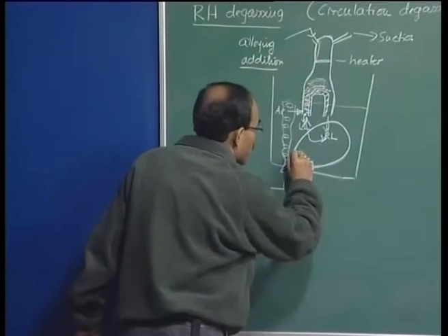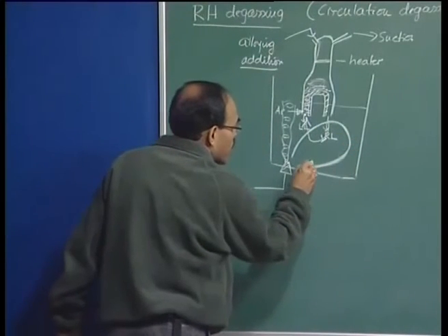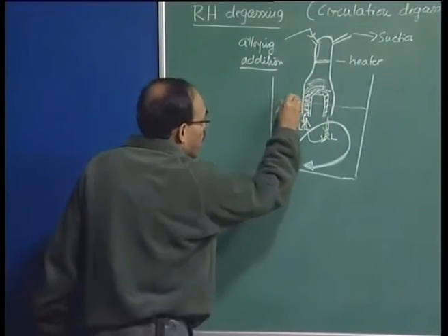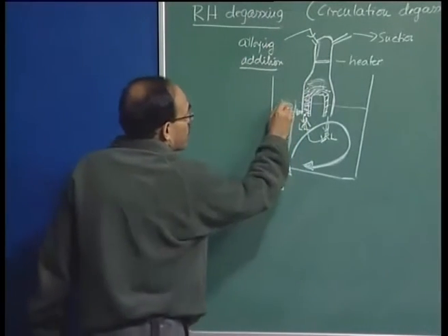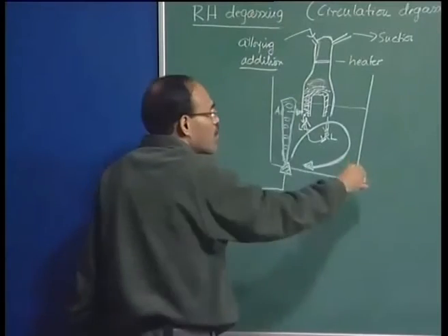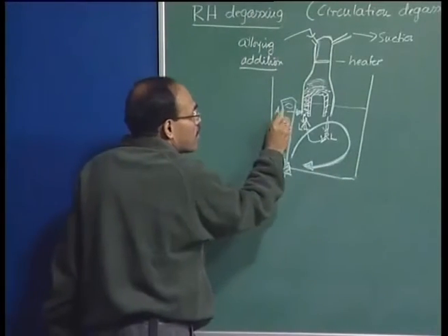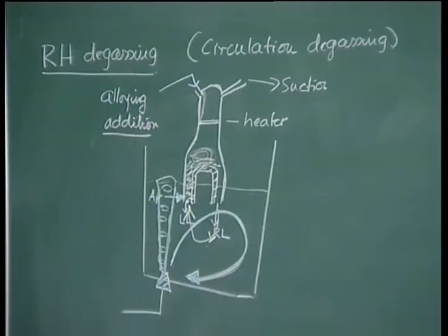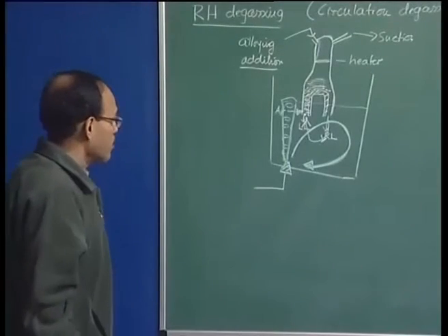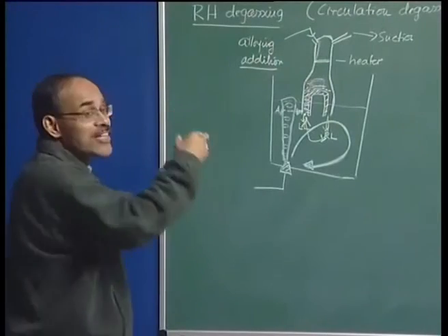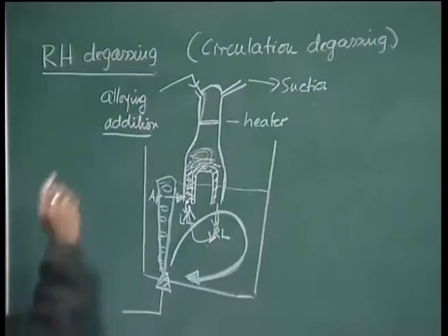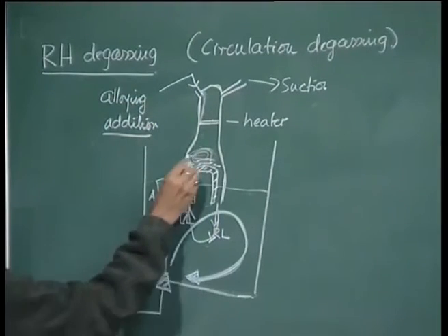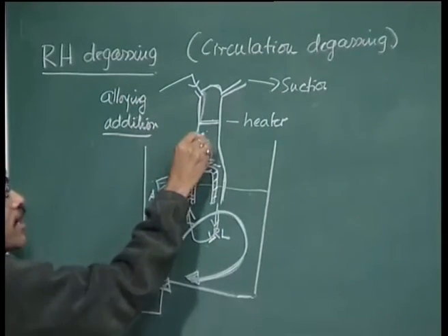process. So, this is the general convection current generated because of the porous plug, and this is the plume, and this plume causes the overall bulk recirculation. On the other hand, this argon, which I have shown being introduced into the left leg, is termed the lift gas, and this lift gas actually draws the material into the vacuum chamber, exposes it to vacuum, and as a result we have metal-vacuum or metal-ambient interaction here.